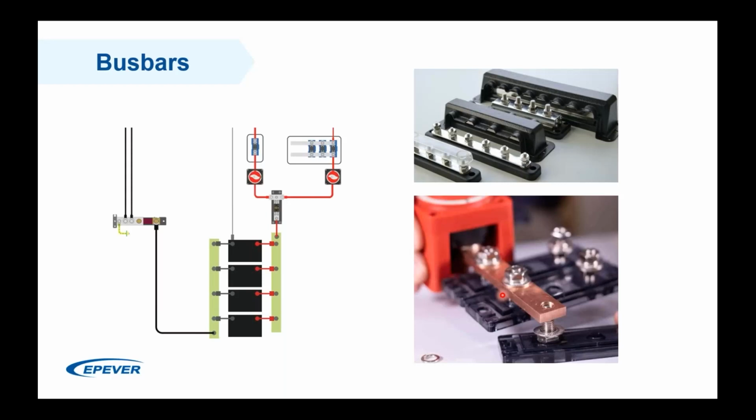And of course, it's recommended to shield the copper bars, especially if the bus bar is in an open area, and there is a danger that someone touches it, or something falls and provides a short circuit between the positive and the negative terminal. So it's always recommended that you cover the bus bars, or you put a thermal shrink over the copper so that nothing will touch the copper itself, and there isn't any danger for short circuits.